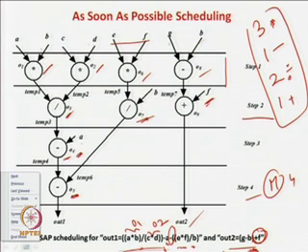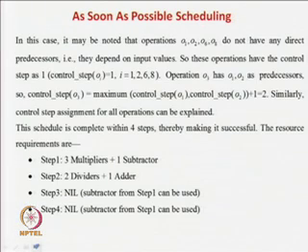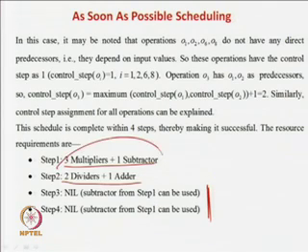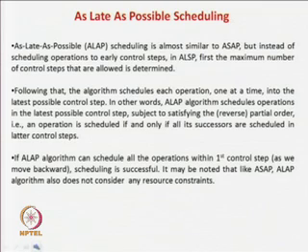Okay. So, now we will go to another schedule. As already said, what are the requirements over here? The requirements are 3 multipliers and 1 subtractor in the first time step, in the second step 2 dividers and 1 adder, and in the third and fourth steps we do not require additional hardware, they can be reused. So, in all these are the resources. Whatever we have already told is listed out in this slide, you can go through it.